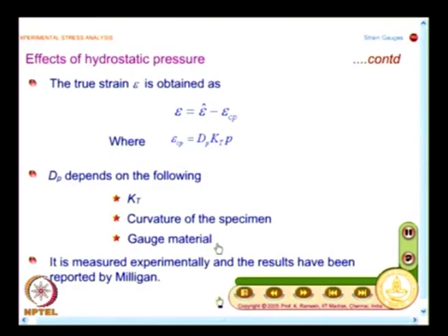See, when you go for finer measurements, the specimen properties matter, the foil alloy properties matter, and also when you are looking for the changes because of the pressure introduced, these changes have to follow a predictable path when pressure is increased gradually. This demanded a very fine installation of the strain gauge on the specimen.